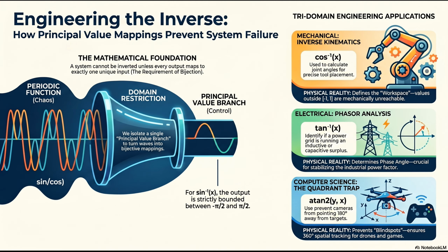If the system treats the inverse tangent calculation without strict principal branch bounding to sort out which quadrant the target is actually in, it suffers a catastrophic tracking failure. Wow. The unconstrained division just compresses two entirely different physical locations into the exact same ratio. So if that second drone is creeping up from behind, the defense system computes the math flawlessly, gets 45 degrees, and points the radar dish 180 degrees away from the threat, literally staring at empty sky. Yes. The fire control system is rendered completely useless, despite doing the math perfectly. The math was right, but the application to physical reality was fatally flawed.